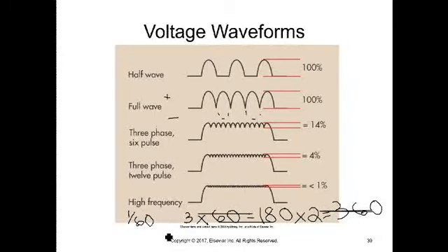So just so that you can see that out, full wave rectified, you use both sides of the cycle, so you have to multiply it times 2. 3 phases goes 3 times through that cycle, so 3 times 60 equals 180, times 2, which is your positive and your negative swing on your cycle, so 360 pulses altogether.